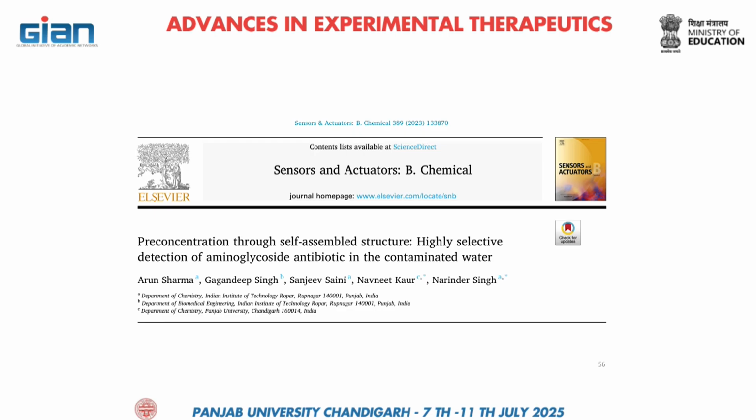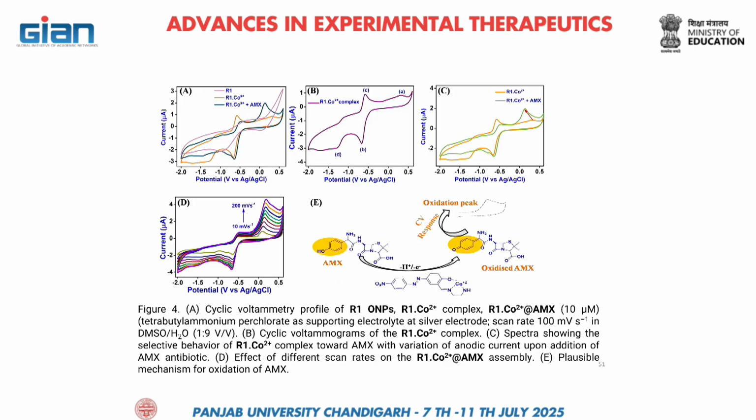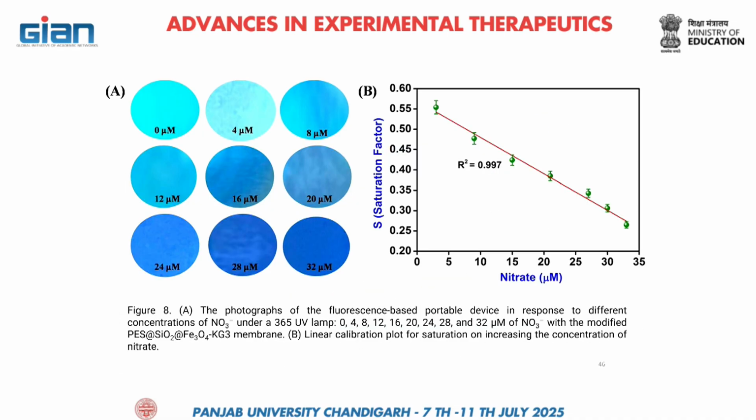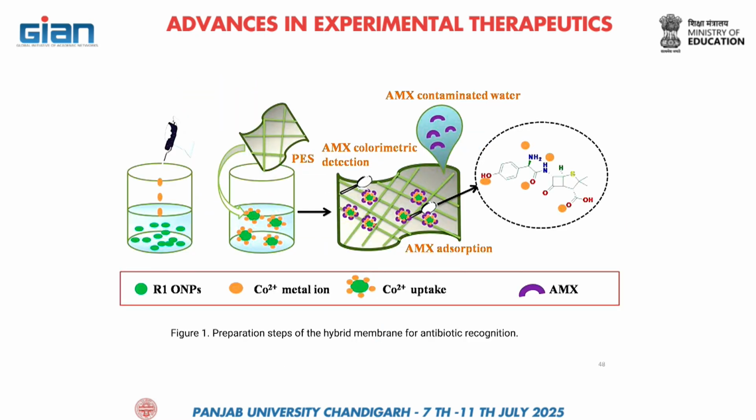So if I combine step 2 in that way, now before going to that, let me show you another thing, why we are doing that strategy. You can see here, if the water has a low concentration of antibiotic, my membrane will last for a longer time. If I have a high concentration, then my membrane will not last long. Now my strategy is, let us put in some chemical which first precipitates most of the amoxicillin, and after that, when there is only a small amount of that antibiotic, utilize the membrane, and then our membrane will last longer.